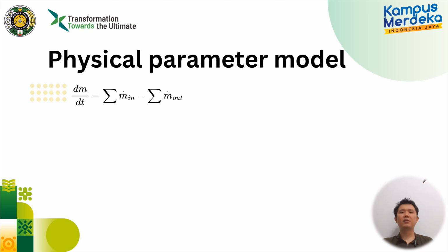Our previous model can describe the mass balance in the unit operation for the related process, but it is still irrelevant for real application. If we inspect our model here, we will see that the variables involved in this model, the mass accumulation rate and mass rate entering and exiting the unit, are usually not measured in real process.